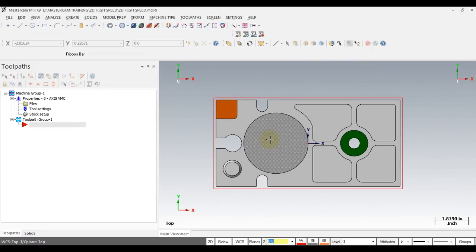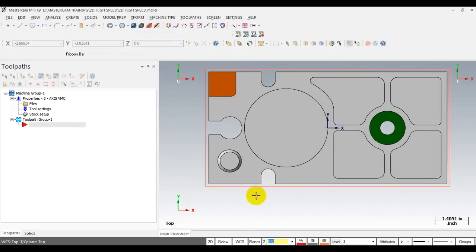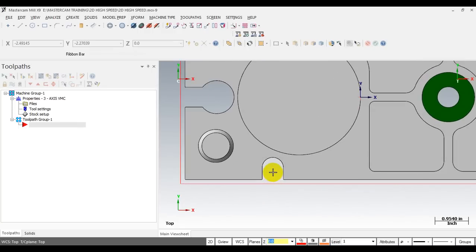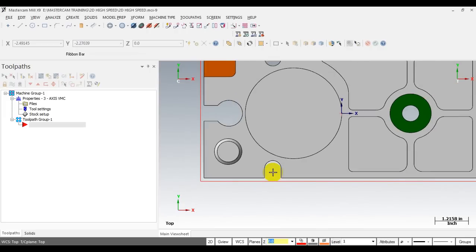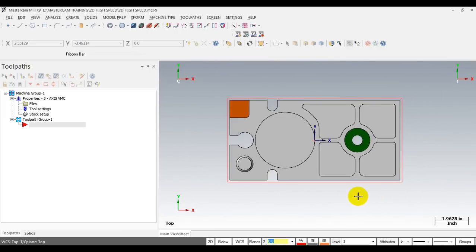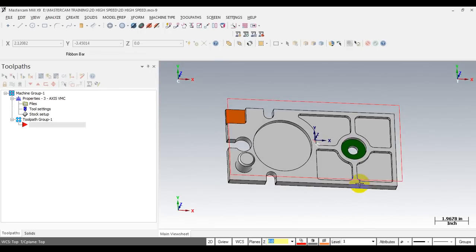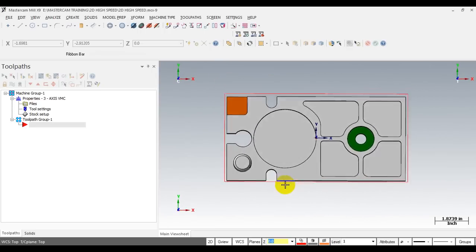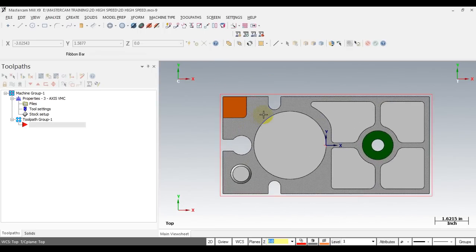That's when we use the dynamic contour. Dynamic contour can be used when we want to remove very little material, but in some areas the material increases. You have a lot of material in just some areas, so you can use dynamic contour in this case. For this outside contour, I can also use the dynamic mill, not only the dynamic contour. I will explain that later.